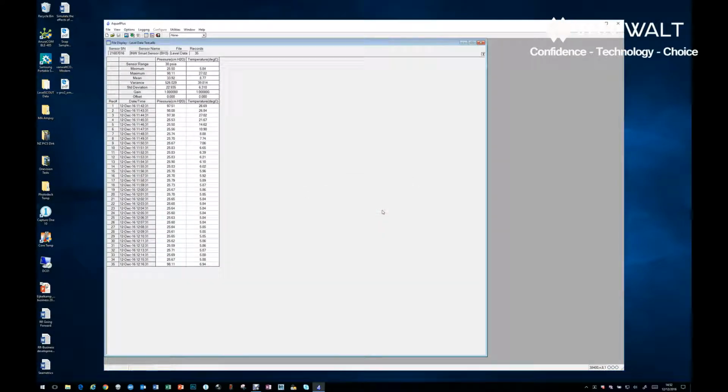So we can view it. Here's our data. We didn't take many recordings here, and it's a relatively boring well. It's just a test rig we have set up, so there's no fluctuation. It's important to note that these first 3 units here are actually our sensor cable length. That is the first pressure reading plus our first manual dip, so that is just reporting our cable length. The reason it does that is because the sensor is in fresh air at that point.